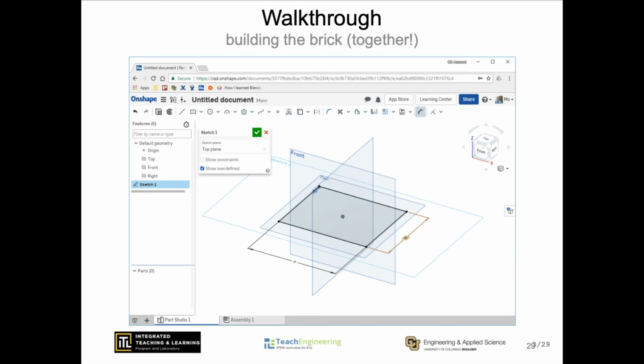Constrain the rectangle. As you can see, we have 5 inches on one side and 2.54 centimeters times 4 on the other side. You can specify different units and even include some basic arithmetic operations in the dimension formula.